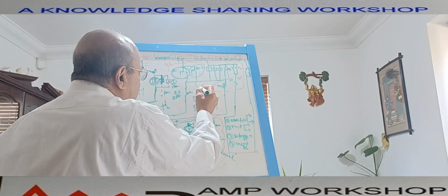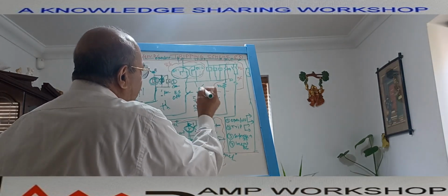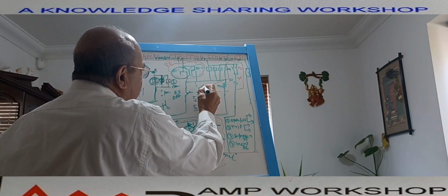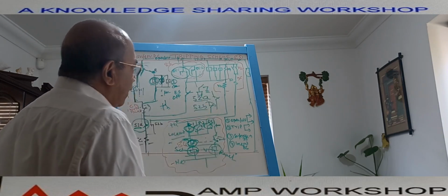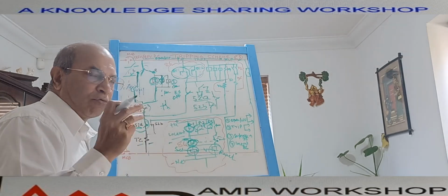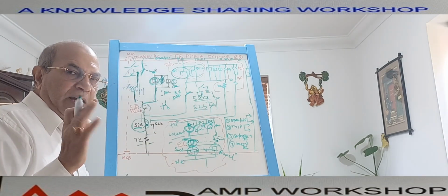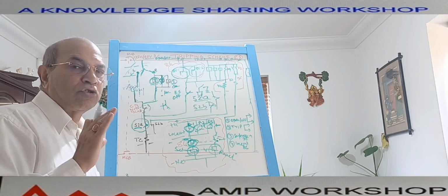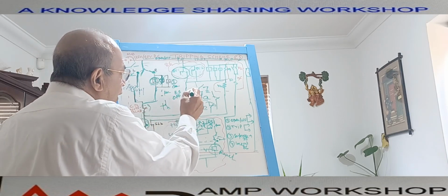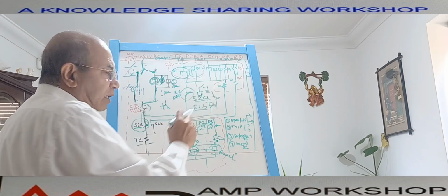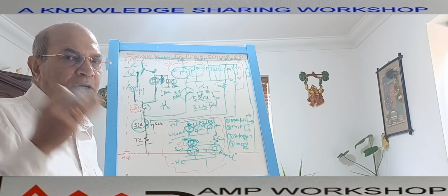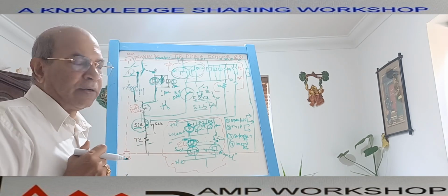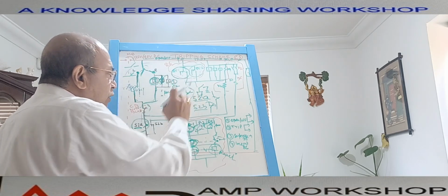There is a disconnector switch, and after that this circuit breaker is there. This disconnector switch has three positions. There is an earth position. When the circuit breaker is going to fault trip, it means the disconnector is on and the earth switch is not on, the earth switch is off. So that interlock we have put over here. The fault trip will not understand what the other disconnector position is. So that's why we put the earth switch off location.